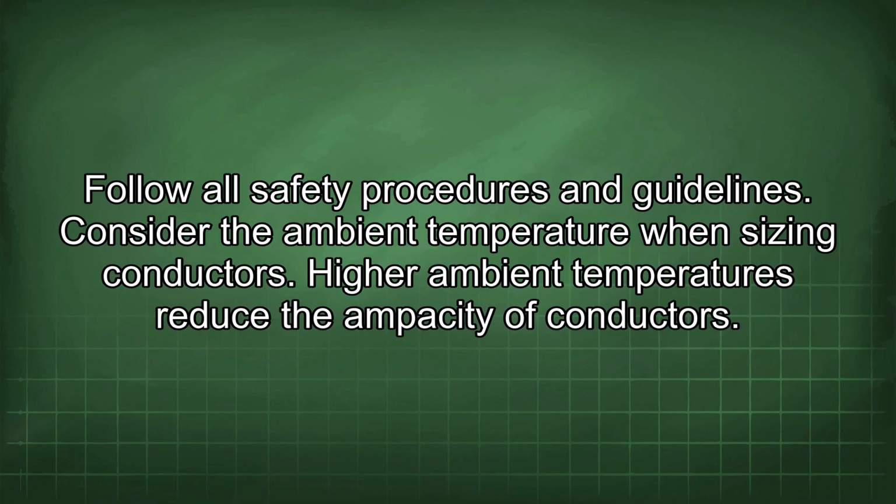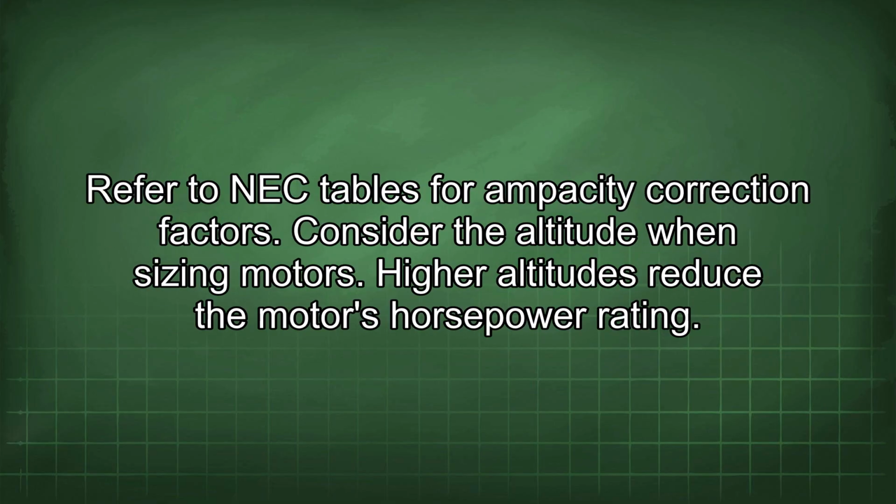Consider the ambient temperature when sizing conductors. Higher ambient temperatures reduce the ampacity of conductors. Refer to NEC tables for ampacity correction factors.